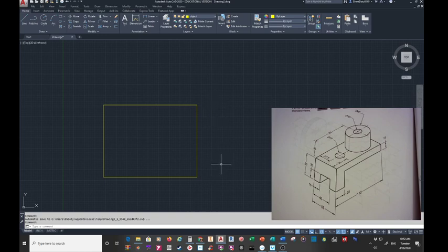and then we go for the depth, which is 55. So I'm going to go up here and make me a rectangle, and I'm just going to hover. I'm not picking, I'm just hovering. This is how you use your O tracking. See, it says extension, object snap, hey.